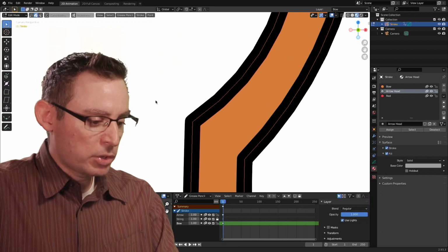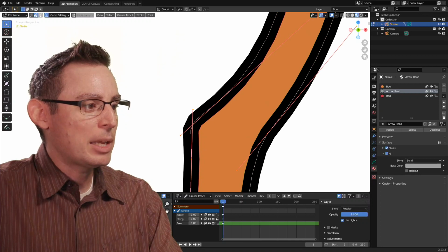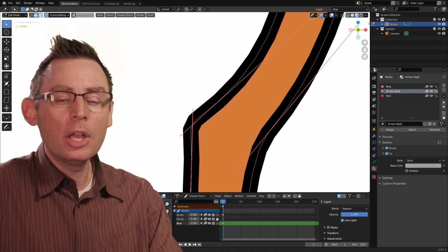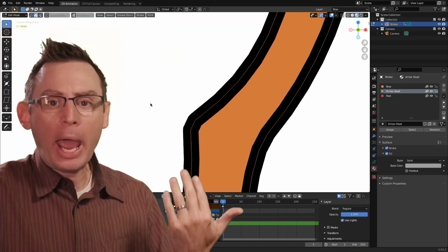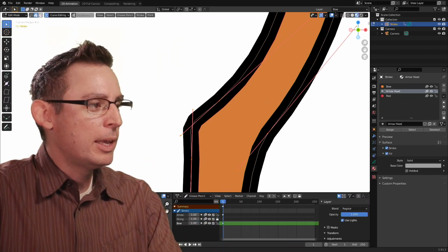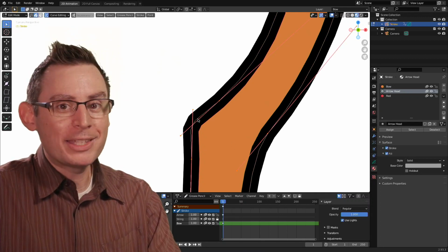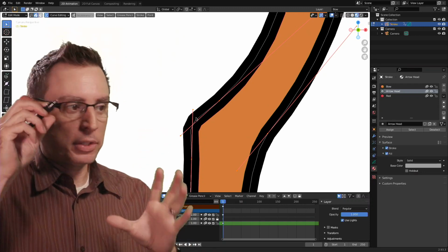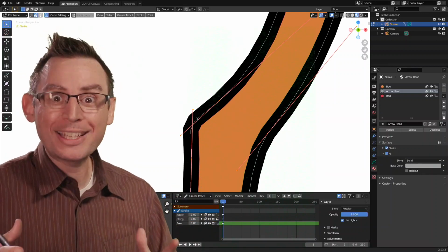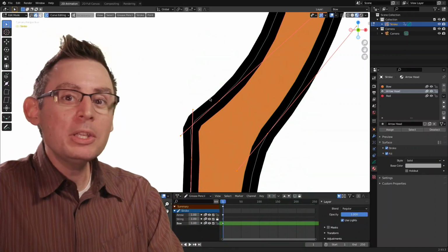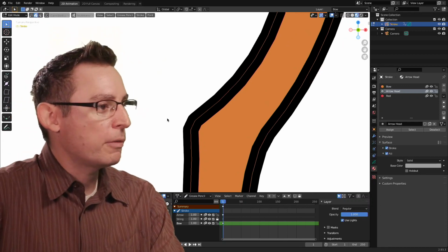Let's turn it on. Here's the great keyboard shortcut, by the way, and one that you're going to be doing all the time. To enable and disable curve editing on a stroke, it's going to be the U key, U as in uniform, on the keyboard. You don't have to do it, but it's a way to very quickly go in and out of the system without having to leave the area of interest and just utilizing a keyboard shortcut. I try to keep my mouse, my pen, right where I'm drawing at all times. It makes me really efficient. It makes the process of animating go a lot faster. So using these keyboard shortcuts is a handy dandy way of just kind of speeding up and keeping it pretty efficient.